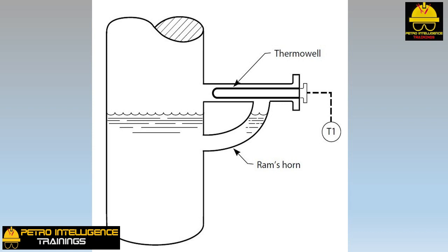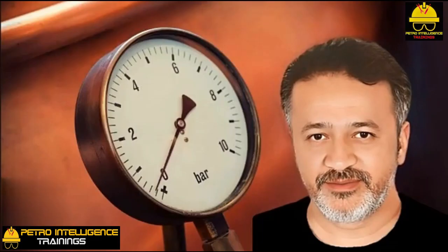If 2 temperature readings from the same point in the process disagree, the chances are that a temperature indication is more accurate than a temperature control signal. The temperature signal used for control has usually been converted from its direct milliamp output to operate a control station. The temperature indication is generated right from the junction of the thermocouple, and hence there is less chance for error.